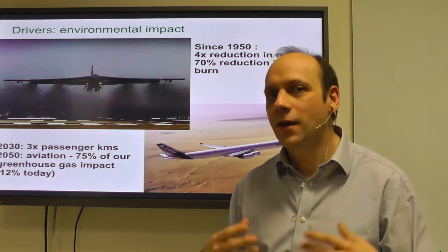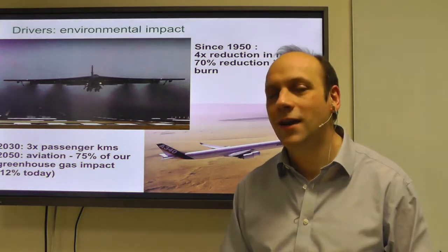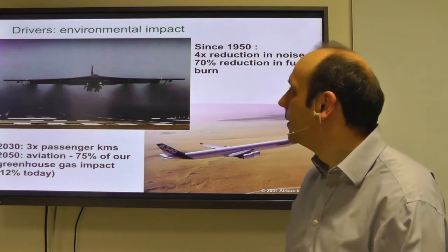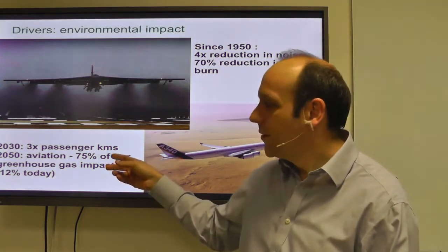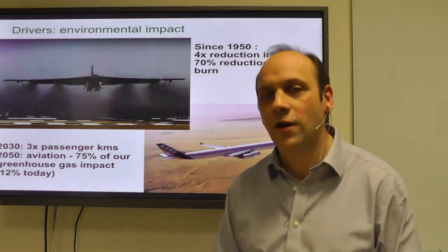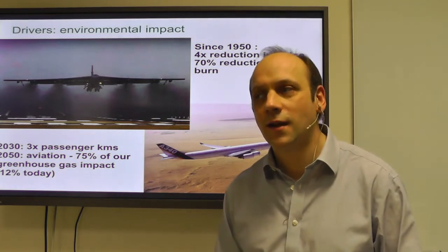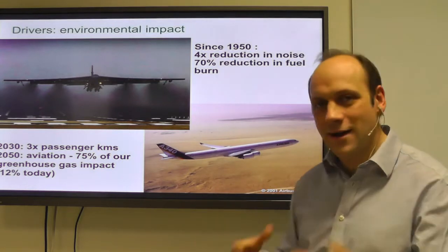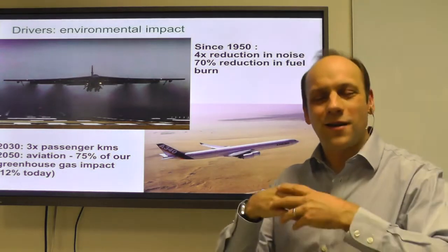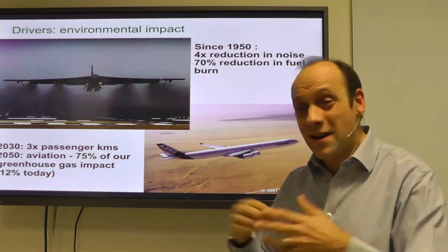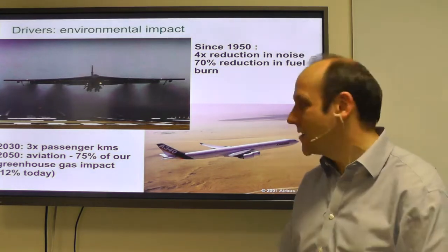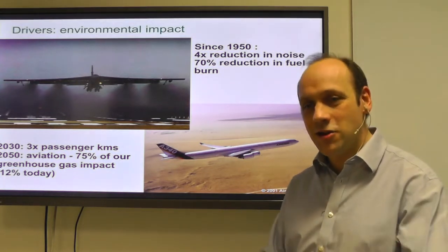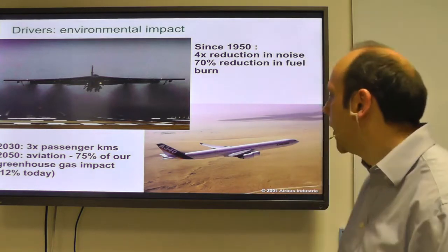If we're only making air transport 1% a year more fuel efficient, well, 1 or 2%, then aviation is going to be a large fraction of our total emissions as a society. And it's very difficult. Kerosene has the highest energy density of any fuel. Things like hydrogen storage are never going to get there. Batteries are never going to get to the sorts of energy densities, energy per unit mass, that kerosene has.